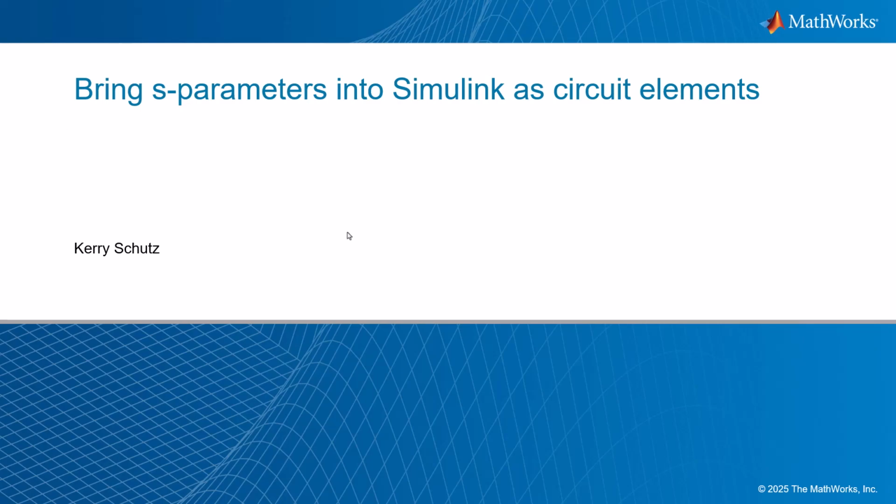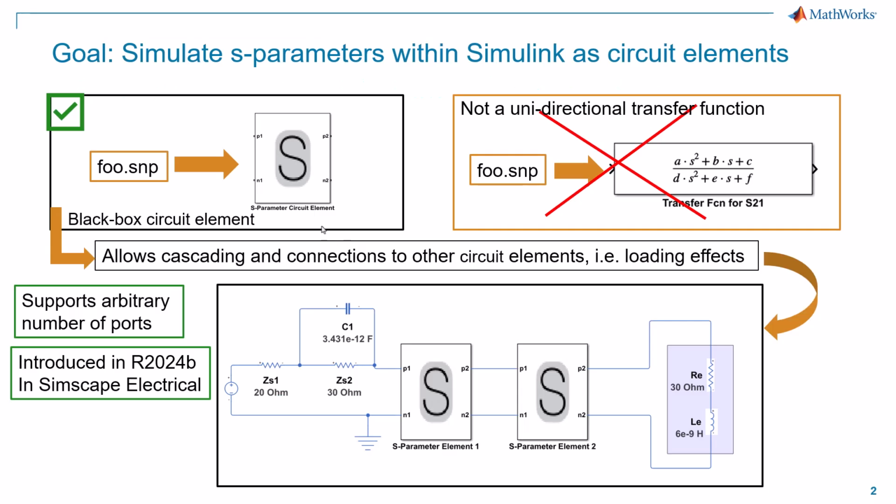In this video I'm going to show how to bring S-parameters into Simulink as circuit elements. So again, this is our goal. We want to start with a touchstone file, and we want to import that, instantiate that into Simulink as a circuit element. And we're going to be using a block from Simscape Electrical to do that, an S-parameter rational